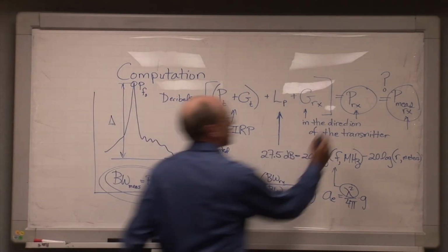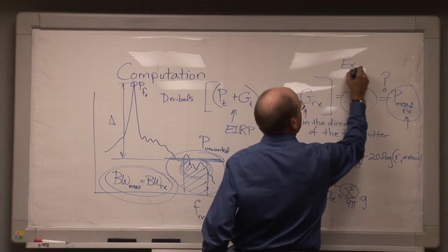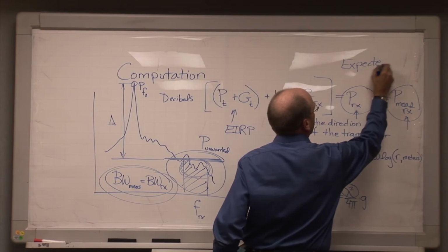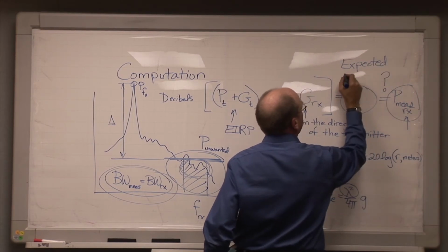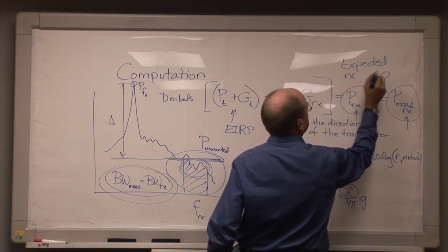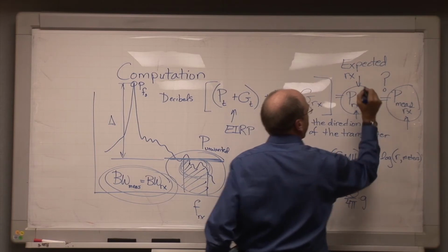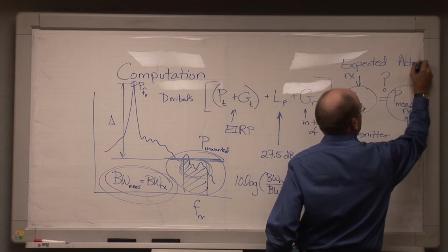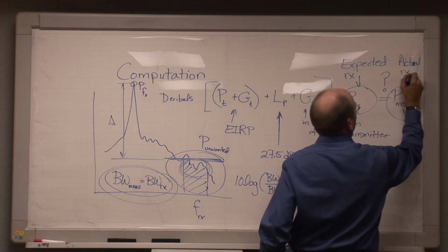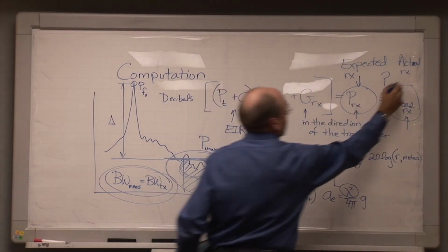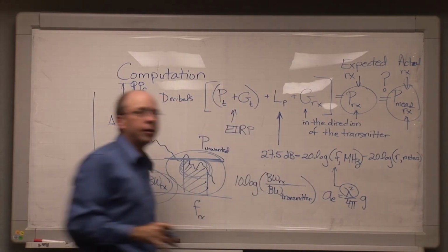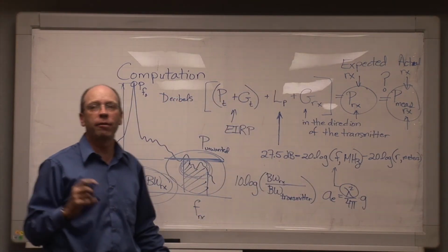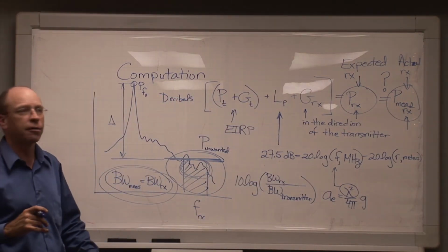In other words, we look to see whether the expected power in the receiver equals the actual power being picked up in the receiver to within a few dB. It doesn't have to be an exact match, but we want to see if it's close, if it's possible.